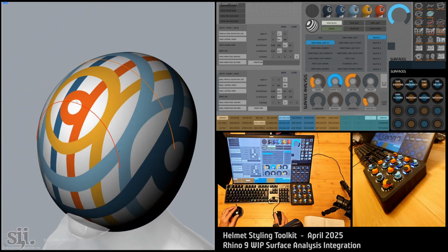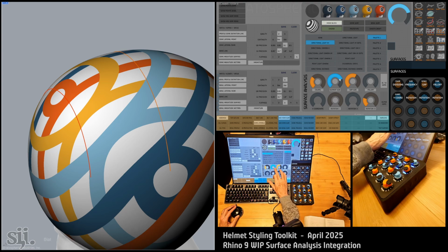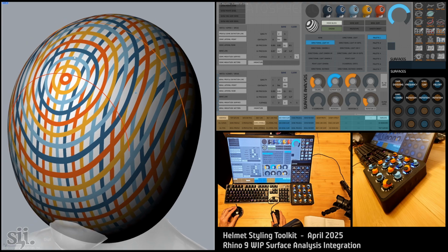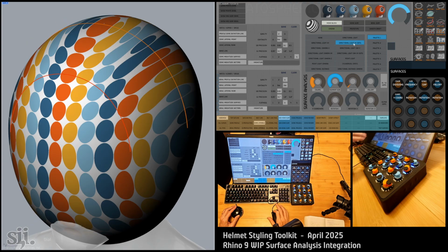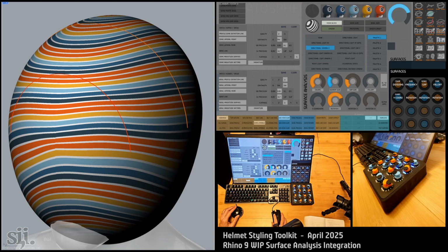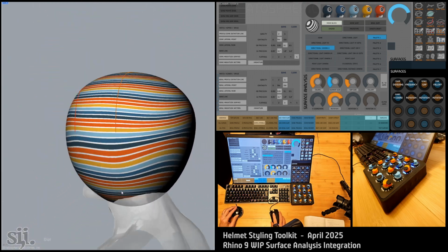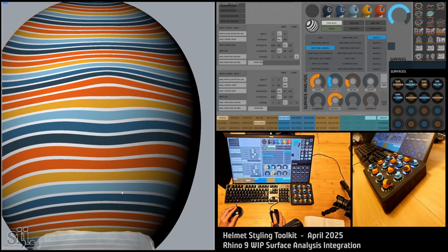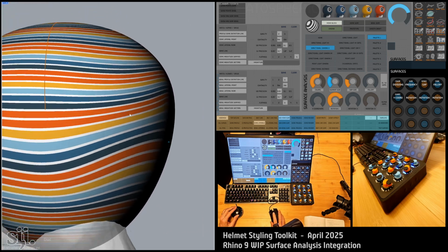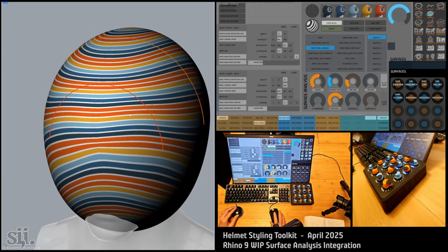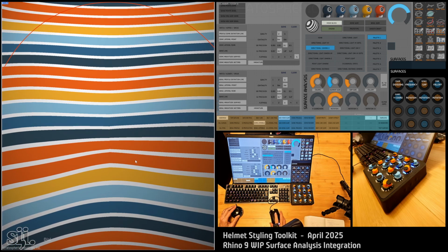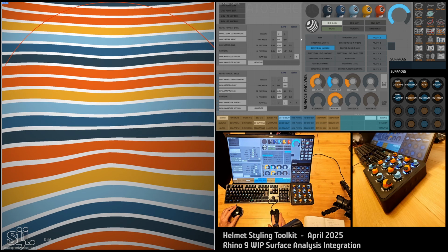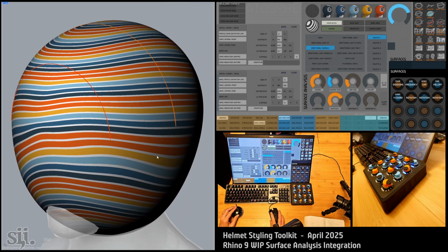Directional light X and Y gives you two different forms. The elements are not individually controllable, so they control in the X and Y directions the same amount. Directional dots we've covered. Directional camera X. Okay, this allows for that view, which is more of a classic view of distortion. So you can see some rapid rates of curvature here. Okay, that's a kind of visualization. We see a little seam right here, which can be tightened up through tangency and increasing the precision of the surface.